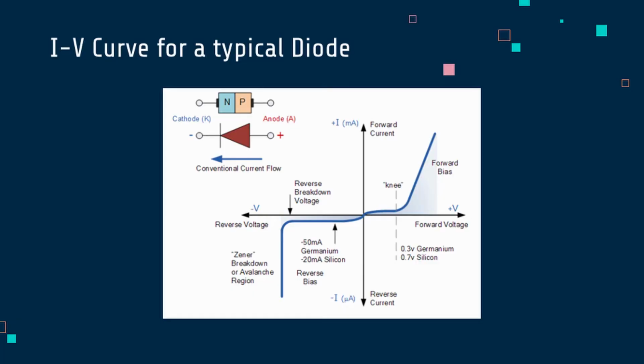Next, I will discuss IV curves, which describe the amount of current that an electrical device has when the voltage across it is adjusted. As shown, a diode has a relatively constant low resistance past the knee and nearly infinite resistance in the reverse direction until it reaches its breakdown voltage. The values for these threshold voltages typically depend on what material the diode is constructed out of.